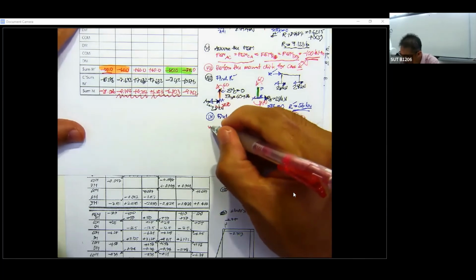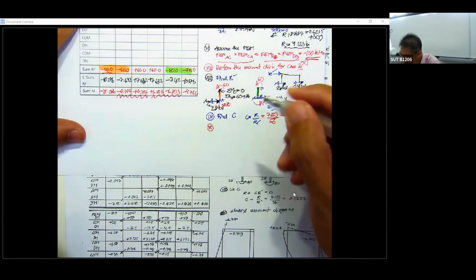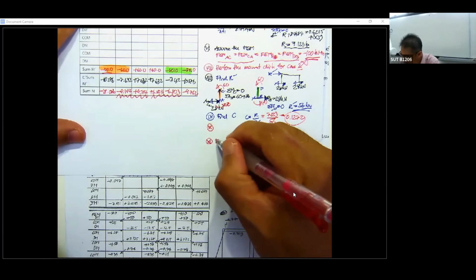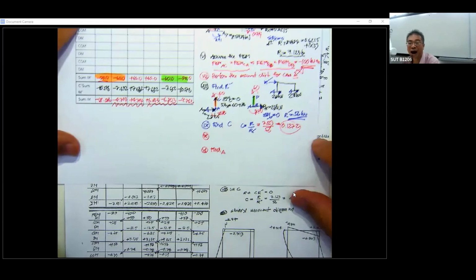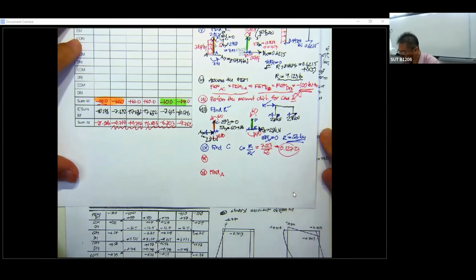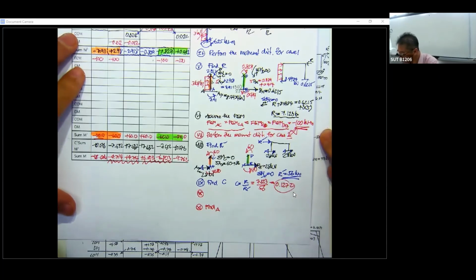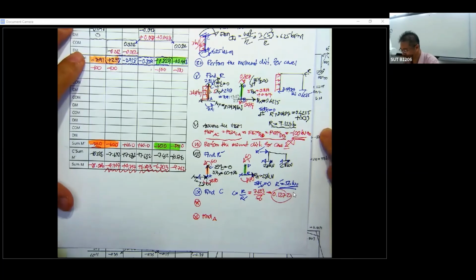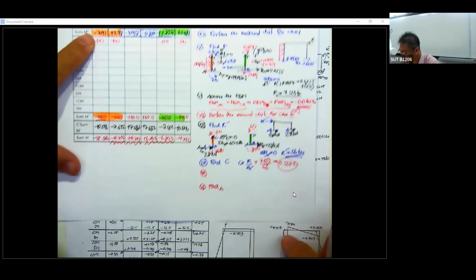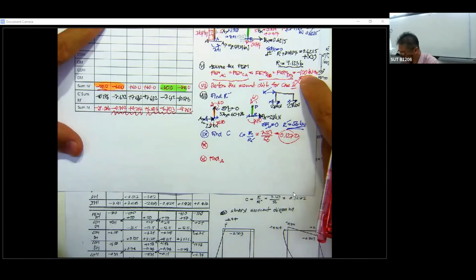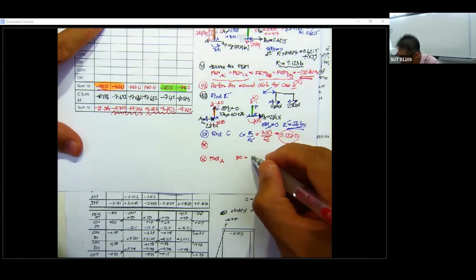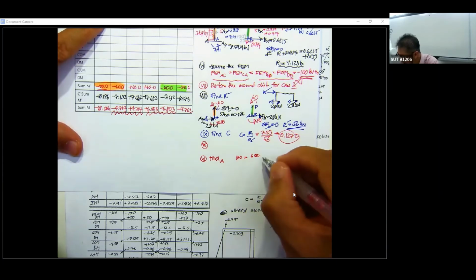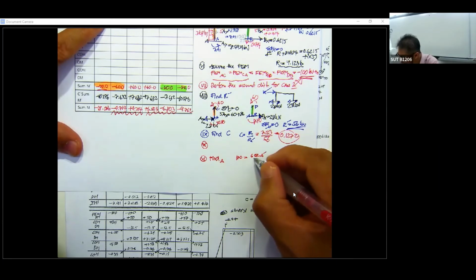And then you also can use your correction factor to determine. That is going to be number 10. Number 11, you can find delta. How can you find delta? When you assume this fixed end moment to be minus 100, that fixed end moment 100 is going to be 6 EI delta prime over 5 squared.